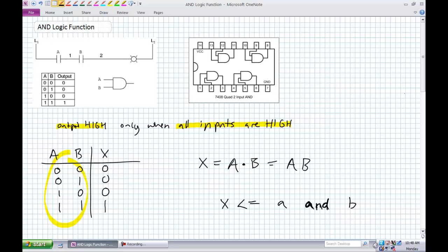Okay, these are keywords that cannot be used as a variable. You can't call a variable and because it's a key word, it's reserved. Okay? Semicolon to close that. You'd use that expression to program in VHDL an AND gate. You would tell that programmable logic device, I want this signal to be ANDed with the other.